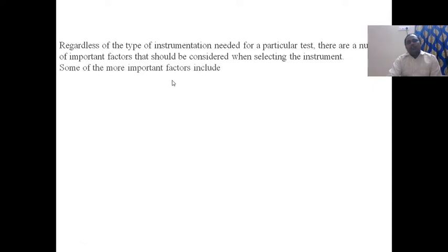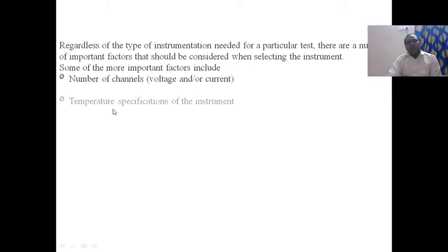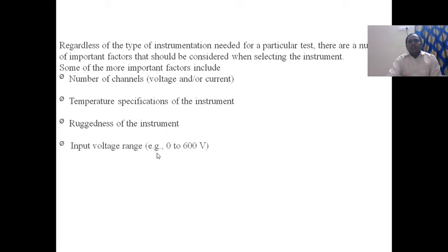Some of the more important factors include number of channels, voltage or current, whatever it is, temperature specification of the instrument, ruggedness of the instrument, input voltage range, that is 0 to 600 volts normally, power requirements, ability to measure three-phase voltages.